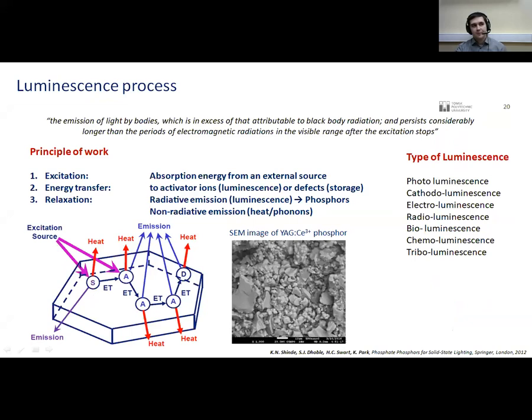I said, when I described the principle of operation of LEDs, there is some terminology like electroluminescence. If we speak about white emission, especially using the phosphor, we should use some really important phenomena like luminescence. The photoluminescent phosphor materials nowadays are an extremely important source of light to fulfill the technological demand over the conventional light sources for an eco-friendly environment. Phosphors in general are powder inorganic materials.